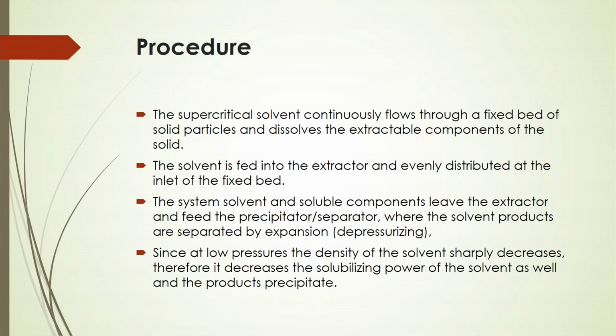This is called the depressurizing condition, and you will see that at low pressures the density of the solvent of course decreases sharply, and because of that it decreases the solubilizing power of the solvent as well, and also causes the products' precipitation.